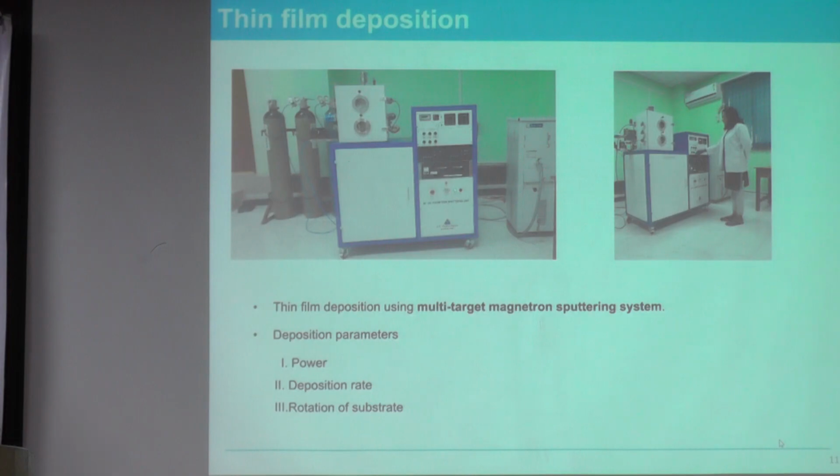Once you have calibrated one material, this is the deposition rate, and then you do multiple measurements with the same condition. Same condition means what? Here it is not mentioned. You can see there how much argon you are providing inside first of all. What is the chamber pressure? The chamber pressure also you need to calibrate. Everything is dependent on that. And if all parameters are constant, then only you will get a uniform deposition.